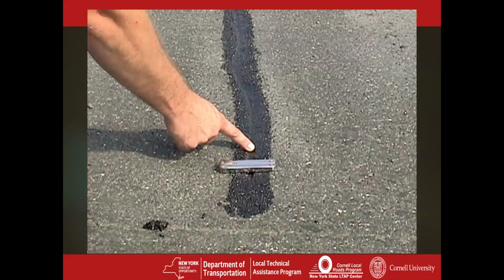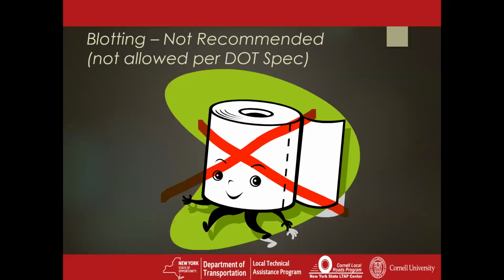You want to be able to put your fingertip into that newly placed material after it cools sufficiently, so that you get a little bit of an indent, and that gives you some room for the movement of that crack during change of seasons, change of temperature.